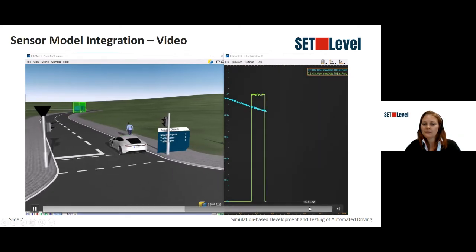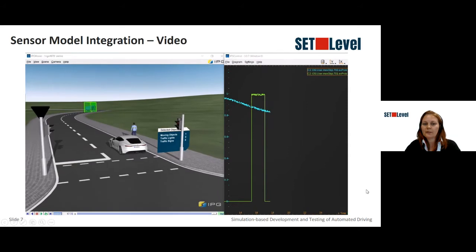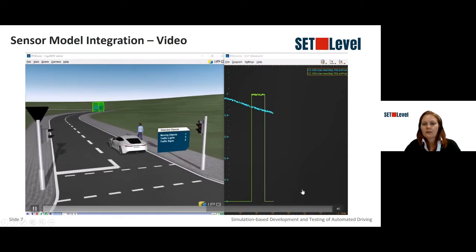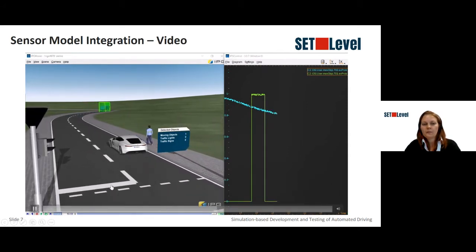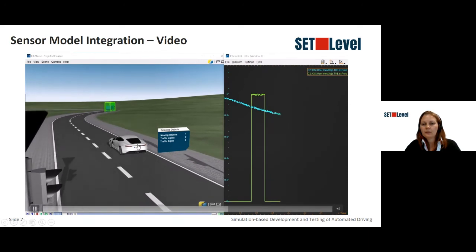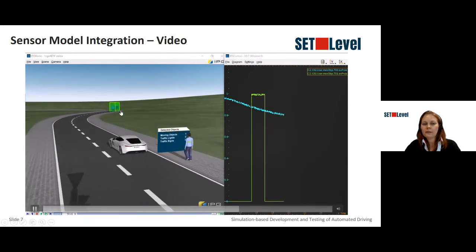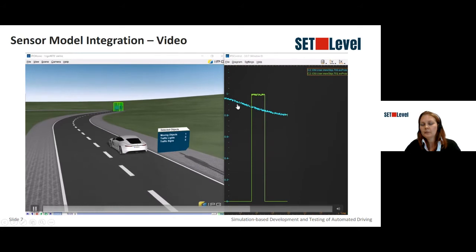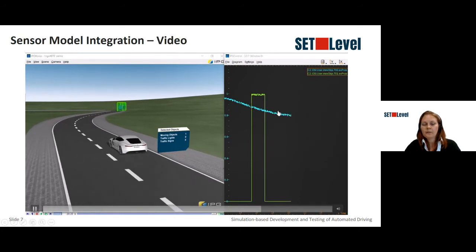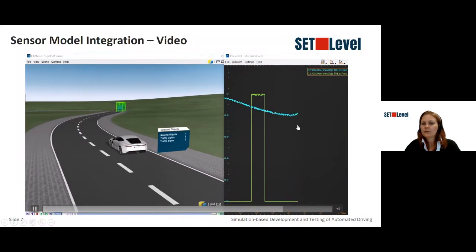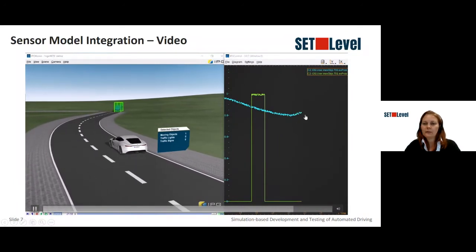existence probability is 0 again, because it's not detected. Also interesting, when the distance to the truck gets bigger, the existence probability falls. And then the car approaches the truck again, and the existence probability rises again to 1.